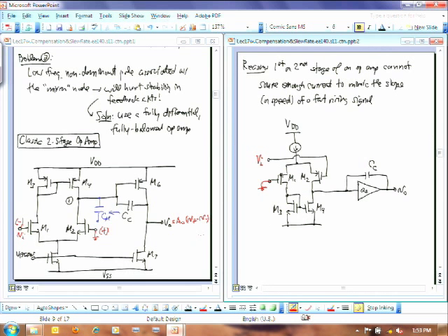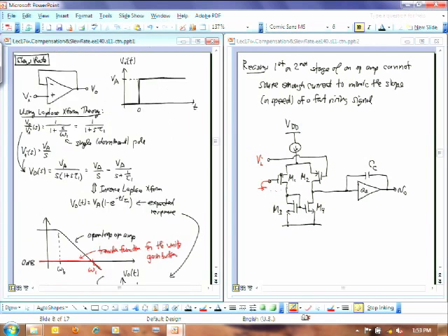What's going to happen is suddenly as its voltage goes up, what happens to this transistor? Not sure? It's PMOS input, so it's a little bit tricky. But it shuts off, right? So suddenly I put a large voltage into that transistor, and M2 goes off, which means the current coming out of M2 is 0.